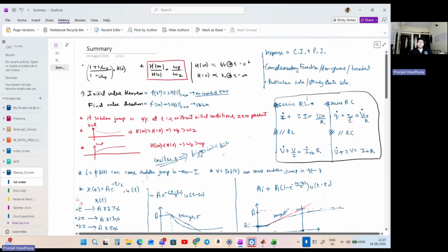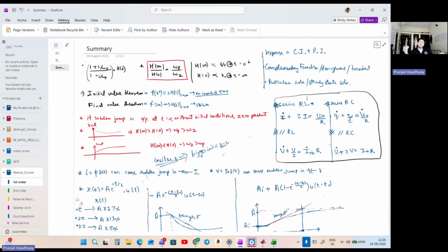Then we know that fundamentally all these RC, RLC circuits are differential equations, right? And because these differential equations are sometimes harder to deal with, we migrated to the Laplace domain to begin with. But when we deal with these differential equations themselves, the response can be expressed by a complementary integral and a particular integral. The complementary integral is also the homogeneous solution, where, for example, if I have this differential equation, this term will be zero, right?